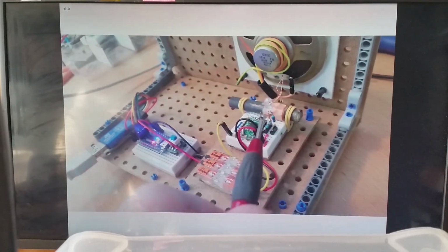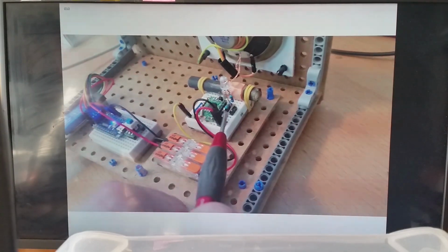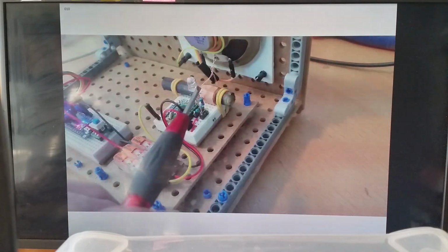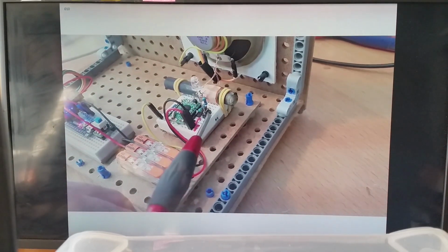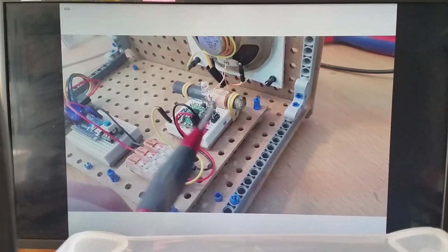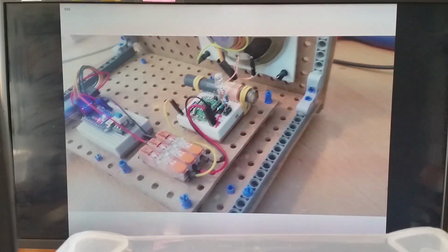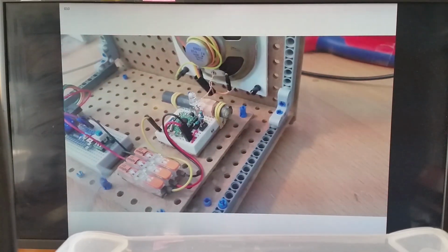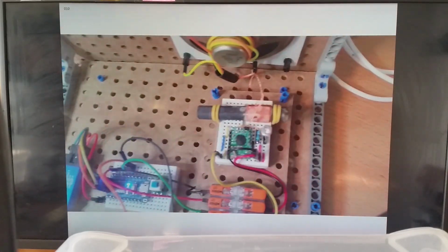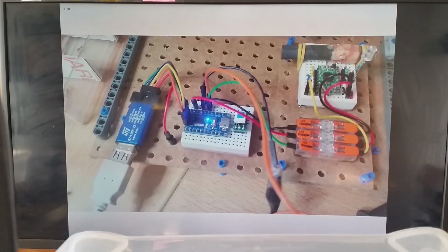As you can see, I soldered the 10K resistor to enable the receiver on a pin header. I always do if I want to make it nice, and also the indication LED is on the pin header, and in the plus signal of the LED I soldered a 1 kilo ohm resistor. So there it is. My LED is blinking. The onboard LED is doing nothing.